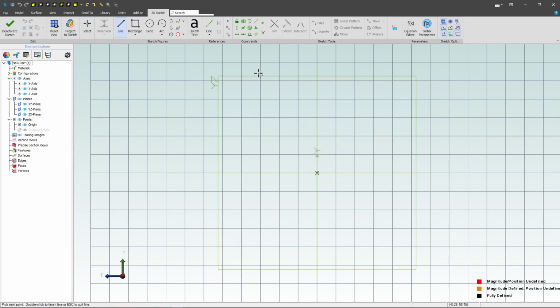moving straight up. You'll notice I have these blue automatic constraints that show up when I click. These make quick work of trying to make a fully constrained sketch and are quite valuable. So making sure that I'm using my automatic constraints, let's now start to dimension this. I'll come to this line and make this a distance of 72 rather.